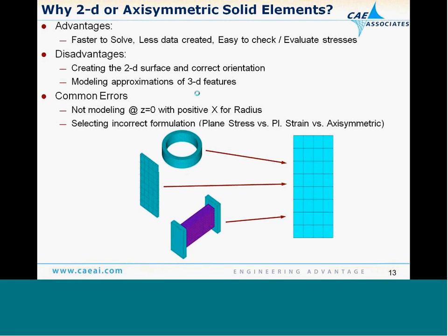From beams, we also have 2D elements we can look at, and 2D elements allow you to get a much faster solution. A lot of axisymmetric problems, there's no accuracy lost in running a 2D axisymmetric model if my loads and geometry and materials are axisymmetric. It's much easier to post-process because we can look at the results directly on the face. We don't have to figure out how it's sectioned to cut open, etc.